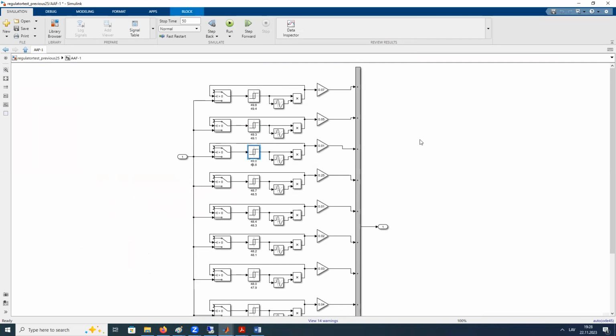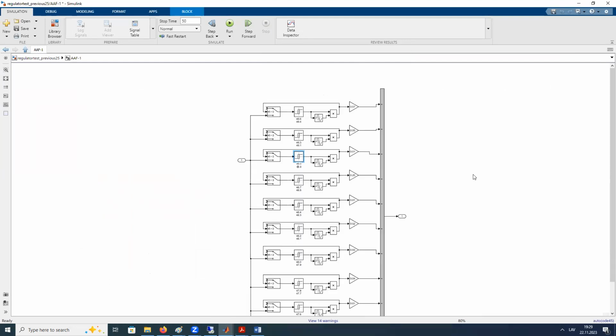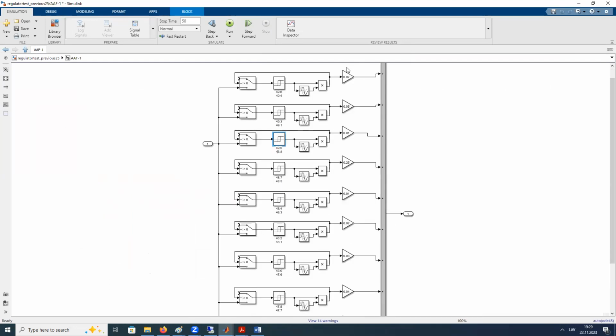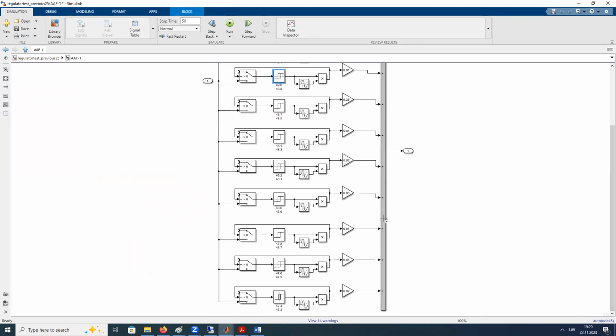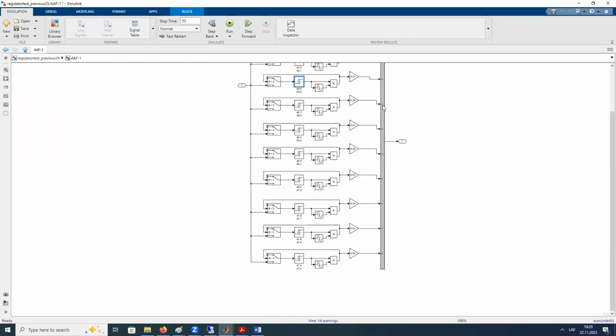Your task will be to find the best set points of frequency and for the load. Here we could see the load. If you sum all these numbers, you'll get the total amount of load connected to the under frequency automation.